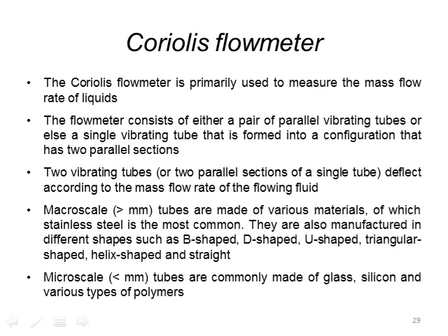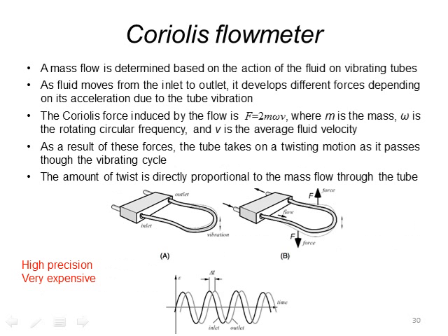So in this case, a tube that's curved into a U shape, this flow is put through this tube, and when the flow goes through this tube at a certain speed, it's going to create, again, this Coriolis force on the tube, and it's going to bend it and displace it. So you're going to get opposing forces. If we look at the next slide, you can see this on the bottom picture.